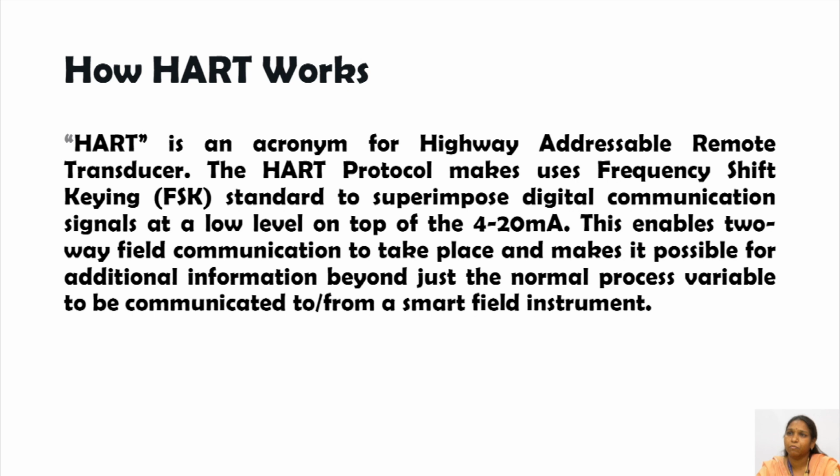HART is an acronym for Highway Addressable Remote Transducer. The HART protocol makes use of the frequency shift keying (FSK) standard to superimpose the digital communication signals at a low level on top of the 4 to 20 milliampere. This enables two-way field communication to take place and makes it possible for additional information beyond just the normal process variable to be communicated to or from a smart field instrument.